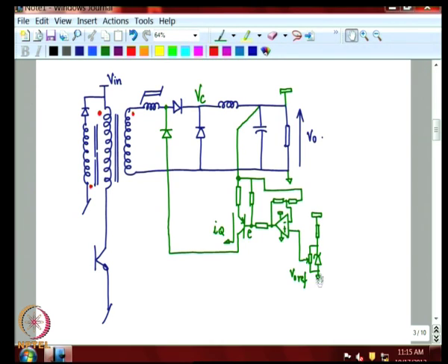This is V0 reference that we are trying to give. So, from the V0 output and ground unregulated, which ultimately gets regulated, you can generate a reference using a Zener, which gives more precise regulation than what you achieve at the output, and then that is given through a pot, and a value is set here. That positive point of the OpAmp, that will be the reference point.